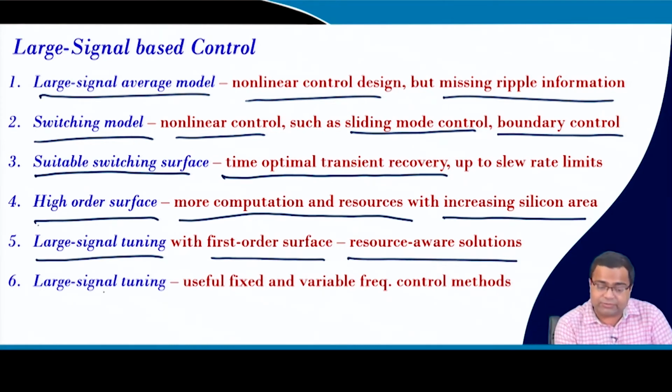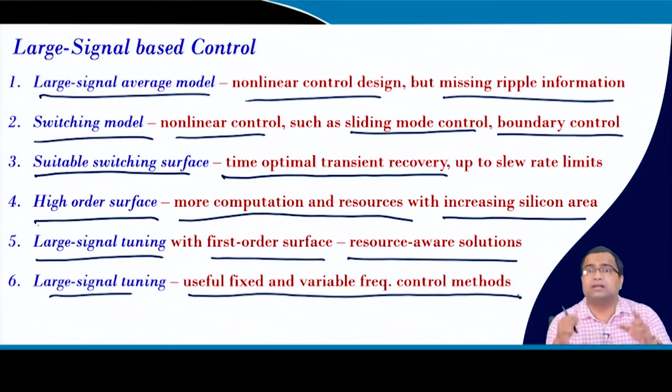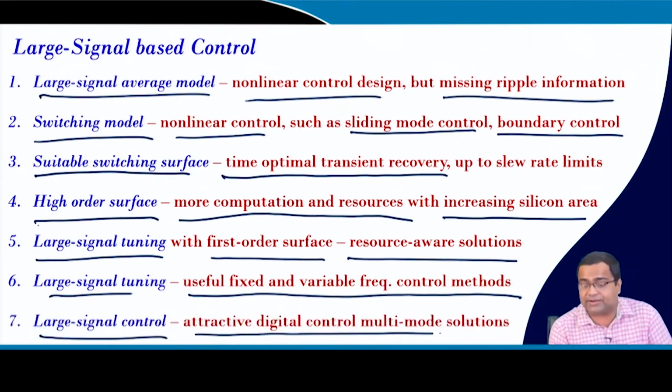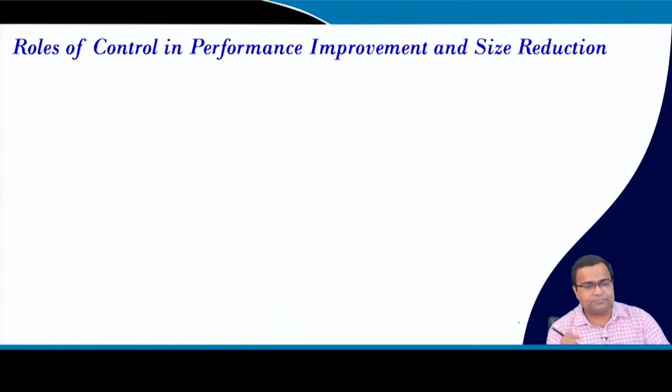And this tuning, we saw, you can apply for fixed as well as variable frequency control, and we have shown some motivated experimental case study. The large signal based control is going to be an attractive solution for digital as well as multi-mode control, and many industries are coming with large signal based control because they want to go beyond the performance of the conventional small signal based design.